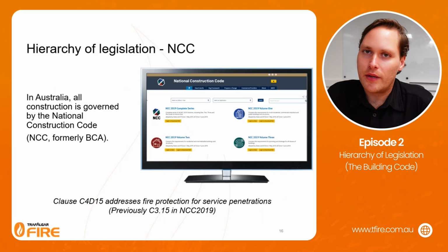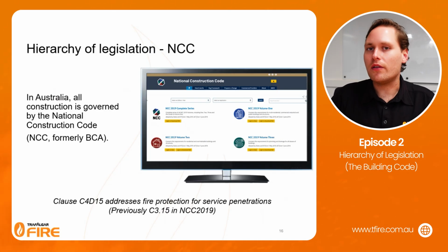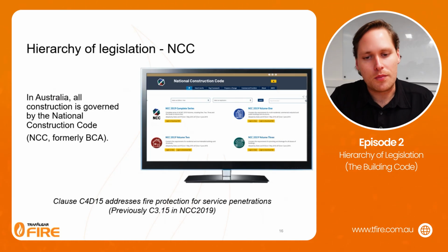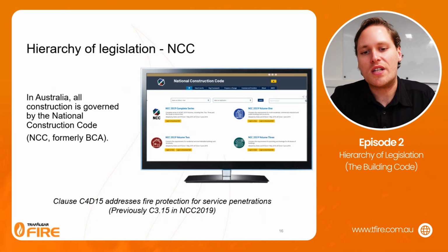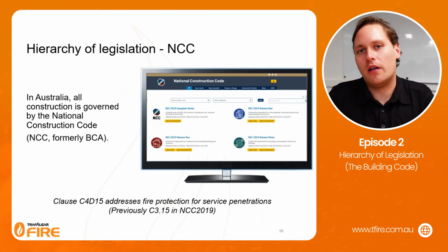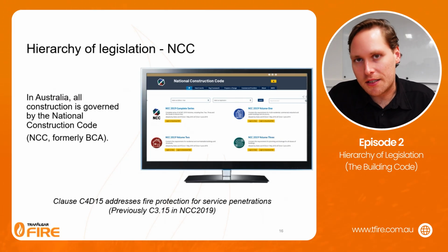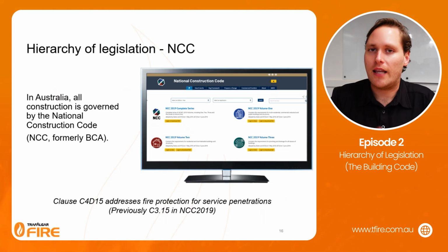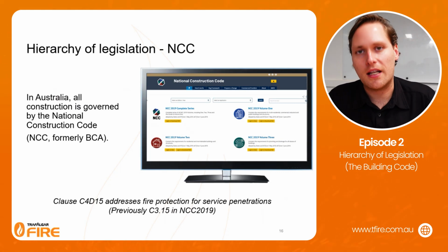Now in NCC 2022, they did update a lot of the code references. So where we're looking at, for example, service penetrations in C4D15, you might be familiar with the clause C3.15 in the previous version of the NCC. Not a lot has changed in the content, but it is worth being aware that the actual names of the clauses have all changed a little bit.